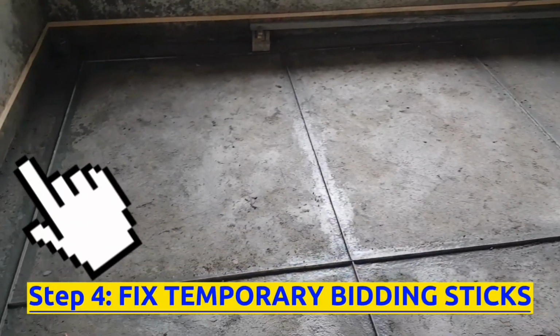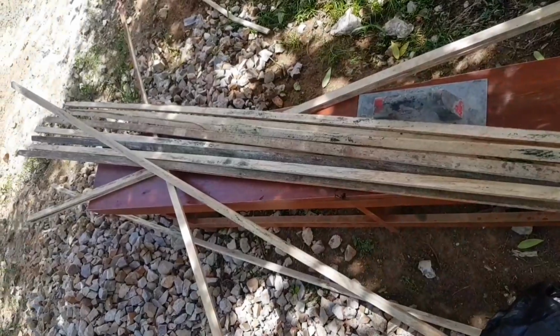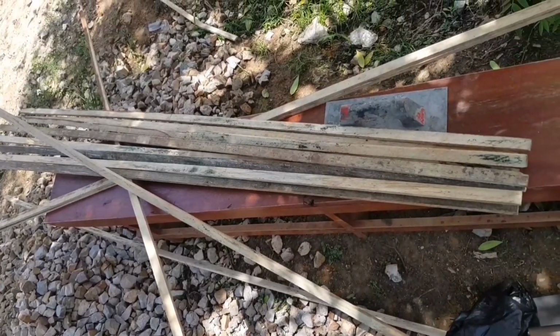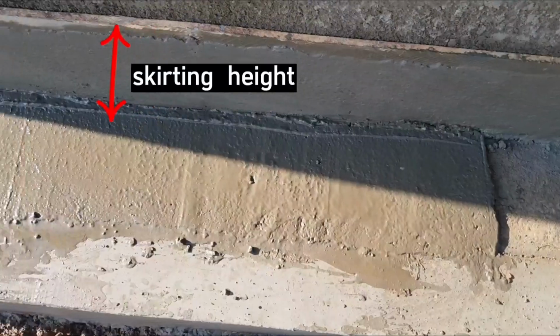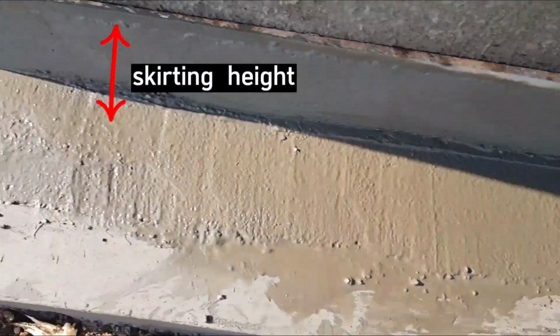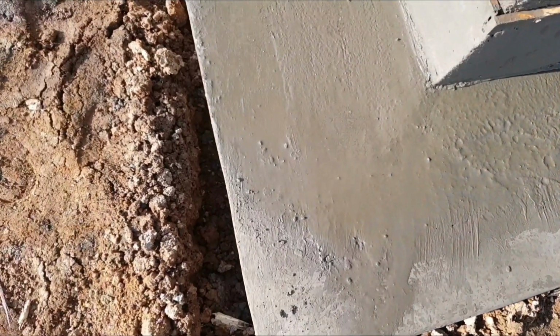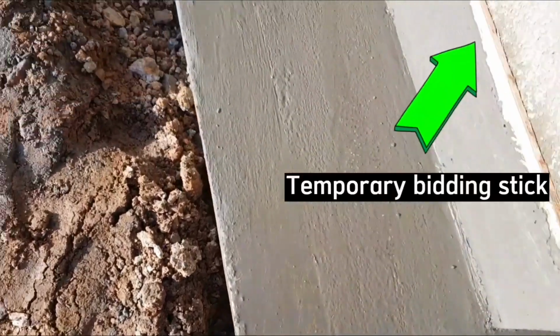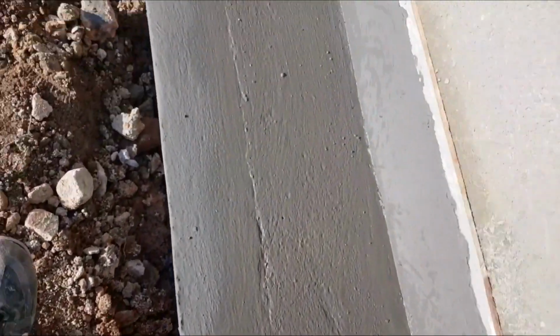Always use that brush. The fourth step is to fix temporary beading sticks onto the walls. These are beading sticks. Their main use is to demarcate a straight line where the skirting stops. So for example, if the skirting stops here at 150 mm from the floor, we fix this beading stick to this level to act as a guide to a straight line for the terrazzo skirting. After the whole process of casting and grinding, these sticks are removed.